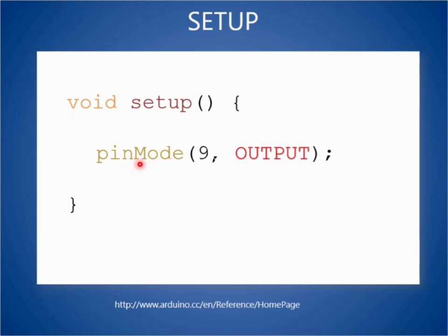Okay, so for this code to run or compile, we have to use this same syntax. अगर यहाँ पे आप M small लिख देंगे तो ये पूरा जो कोड है ये काम नहीं करेगा. Okay, so we have to be very careful about this. So this is to be written like this only, and here you can see we have selected a particular pin number. 9 here is referring to the pin number of Arduino which we have assigned as output pin. उसको हमने ऐसा assign कर दिया है कि pin number 9 जो है वो हमारा output pin रहेगा, and that we have written under void setup जिसमें हम input devices और output devices के लिए pin को जो है assign करते हैं.